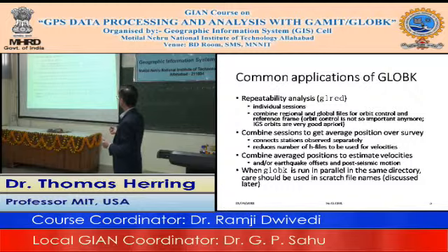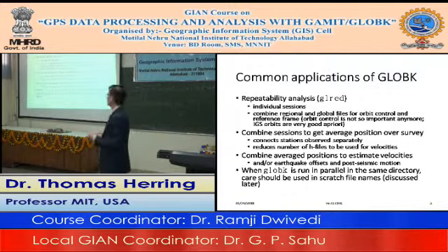This is partly for orbit control, and again, that is not so critical anymore. Essentially anything post 1996 or so, the orbits that come from the IGS are going to be better than anything you will be able to generate. And even now, the IGS orbits are done with a few hundred station networks. They're a combination of 8 different analysis centers. They average out a lot of the errors that happen. So it's very difficult for even us at MIT to do a better orbit.